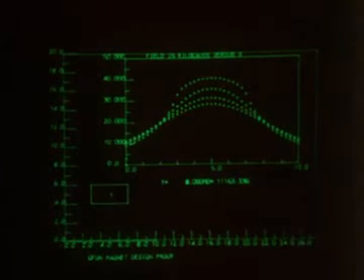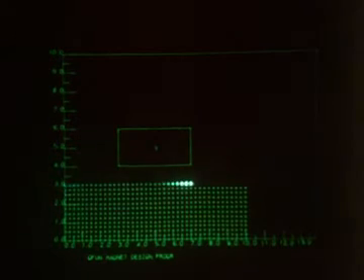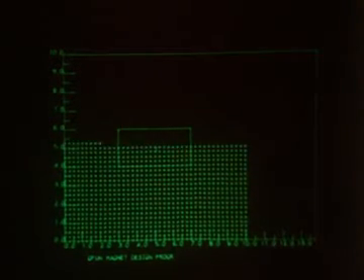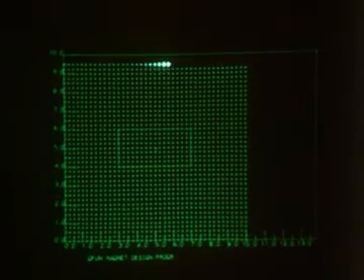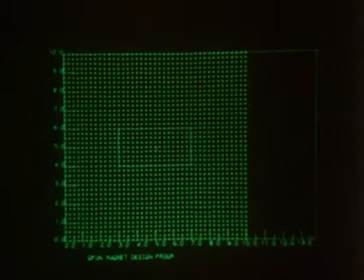To obtain a general description of the solenoid field, a mapping technique is used. After changing the scale of the picture, the designer requests the program to compute the field for a number of points distributed regularly over a rectangular region. For points inside the coil, the computation is more complex, and it therefore takes longer. As soon as the field computation is complete, the designer initiates the contouring process, which interpolates the fields and draws lines of constant field.